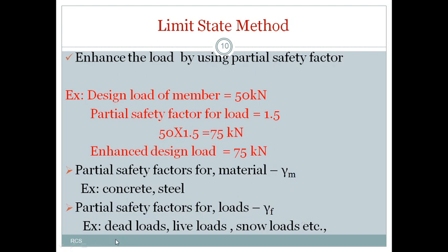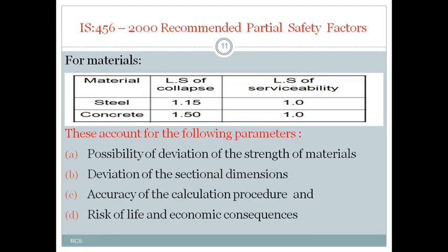For each load there is a separate partial safety factor. Dead load is separate, for live load we have a separate partial safety factor, and for snow load, similarly for earthquake loads. Those are given in IS 456-2000. From that code we can calculate the total load, or total enhanced design load. Right? Here are the recommended values of partial safety factors as per IS 456.